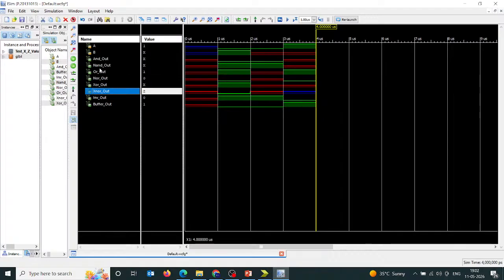While writing the Verilog and VHDL code, they may have set the output Z in case of this input. That is why I am getting Z here. But I already proved that in case of 1 and X, practically on paper I am getting output X. Let's take the example of A and B, 1 and X, and X and Z. So let's solve this.